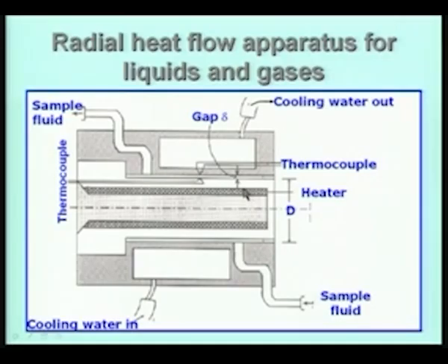Okay. The theory of this is very simple. I have a diameter d which is typically 25 millimeters or maybe a little more, maybe 40 millimeters, and the gas gap thickness is very small, sub-millimeter. Therefore, we can assume that the layer here is almost like a planar layer, because the area change from inside to the outside is so insignificant. If the diameter is very large compared to the gap, if delta is very small compared to capital D, we can assume that the gap is just like a planar layer